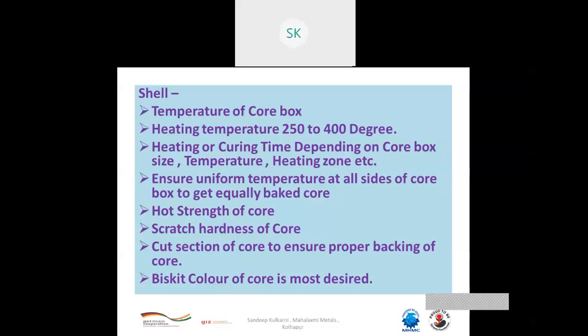Hot strength of the core is important. You have to measure it. Scratch hardness of the core and a cut section of the core ensure proper baking of the core. And most importantly, biscuit color is most desirable.